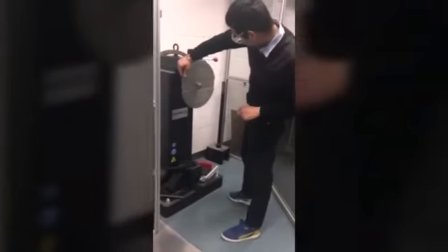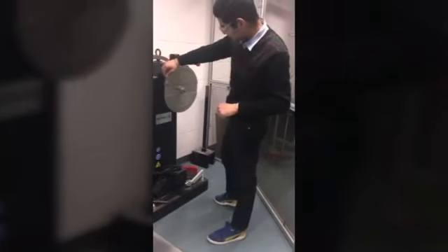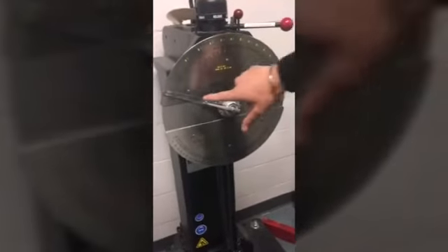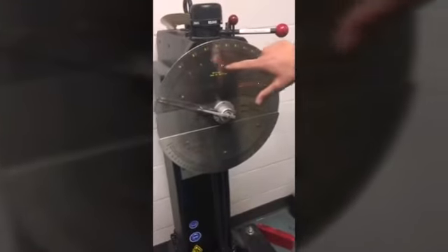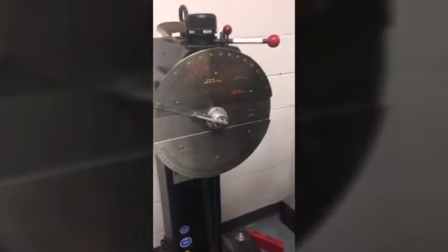After tightening it up, make sure your pointer is at the 54 foot-pounds. We have to see the readings that are in the orange color, as my friend will show you, the 50 and 40 and 30, and this will give us the impact energy.